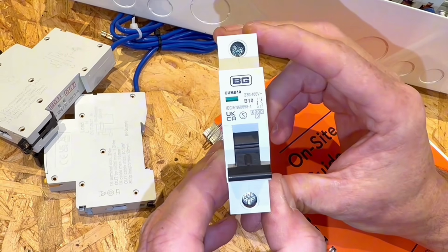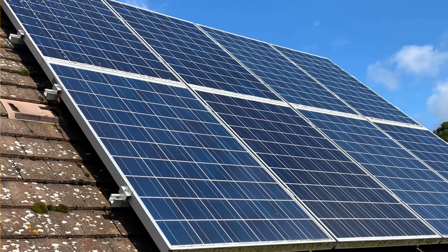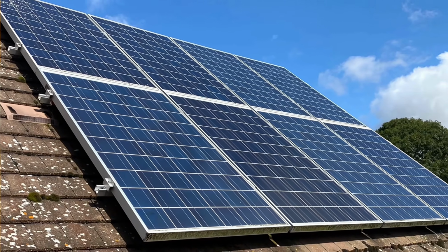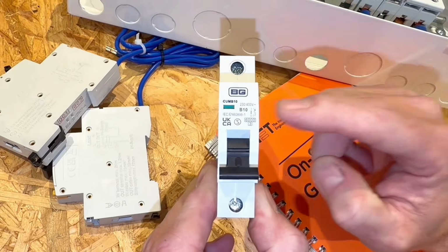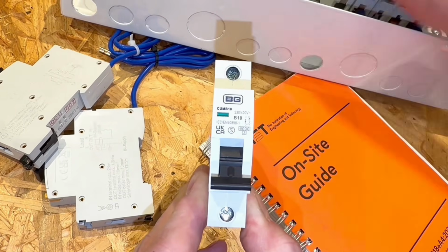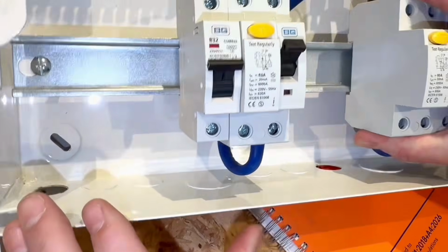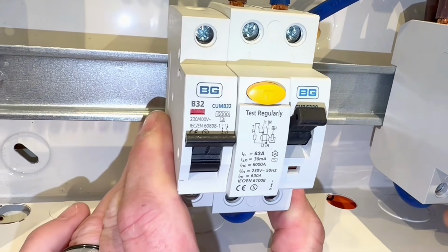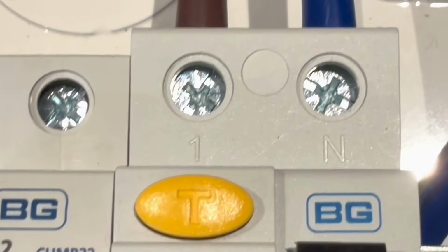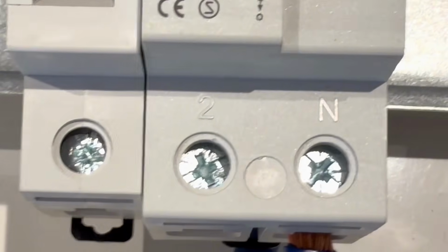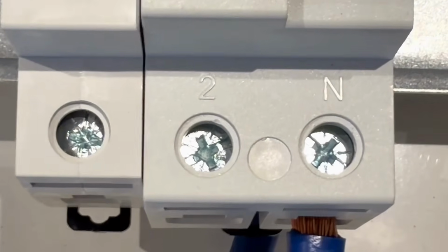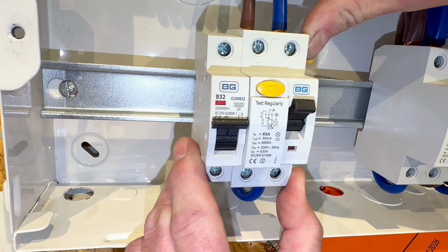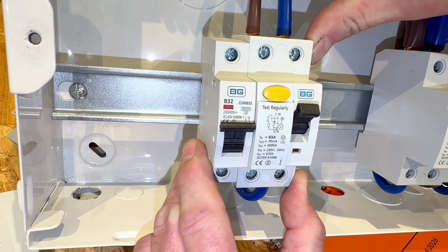So in older installations where, say, solar was installed the first time the boom came around, it could have been in one of these types of boards. This device by default was actually bi-directional, but then we've got the RCCB to look at. So let's look at that next and bring that back in. Our RCCB here, we've got to work out whether this is bi or unidirectional. It says 1 and N on the top, it says 2 and N on the bottom, and then we've got our MCB. Because it isn't defined in and out, we know that this makes this device actually bi-directional.